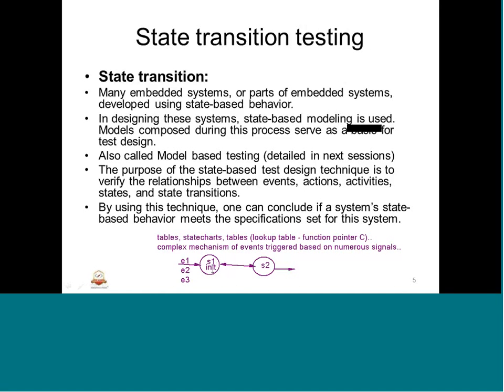Once the init state is complete, that means there are different activities, such as initialization of hardware, software, etc. So this state will be complete. Once the state is complete, that means the actions that are to be concluded within the state are done. So we are good for going to the next state. That means the exit criteria is satisfied, and the entry criteria in state 2 is satisfied. Here it is entry, here it is exit. So we know that state 2 is entered.